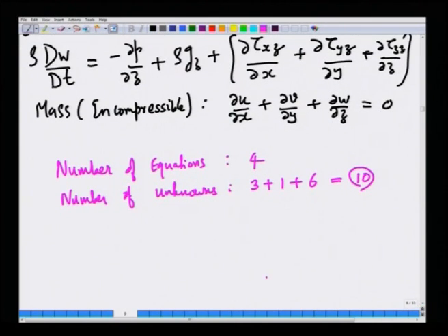We also commented that this mathematical problem stems from the physical reason that we have still not prescribed or stipulated what the material is. We have merely carried out a momentum balance, by applying Newton's second law for a control volume, and by taking the control volume to be infinitesimally small. We have merely stated Newton's second law of motion for a substance, but we have not told what the nature of the substance is. This holds equally well for a solid as it does for a fluid.